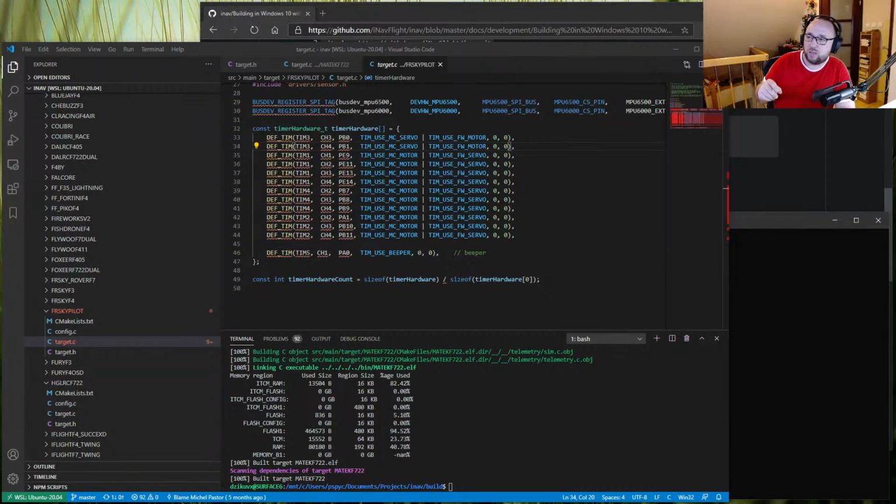However, I don't remember the exact frequency, but I think OneShot is 2 kilohertz and Multishot is above 8 kilohertz. I think so. I don't really remember the exact value. It will try to put this signal on the servo. The servo will either work or will fry itself by trying to adjust and reading complete garbage, and this actually can destroy your hardware. It is possible for the servo to just be destroyed in the process of connecting a servo to a motor output.